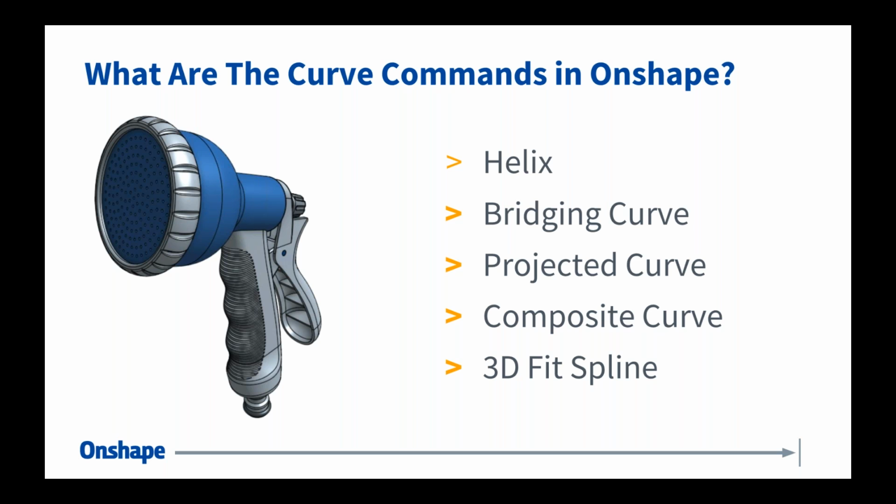So what are the various curve commands? Helix, that's the most common, of course, and the most used. It's been around the longest, and as you can imagine, used to generate all kinds of different helix-driven shapes, things like springs and threads and so on. So helix is the first curve that we're going to discuss here today.